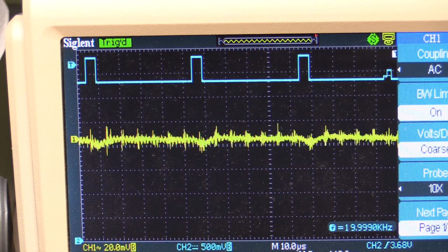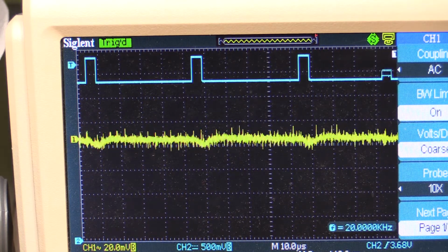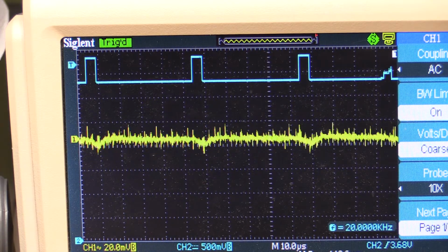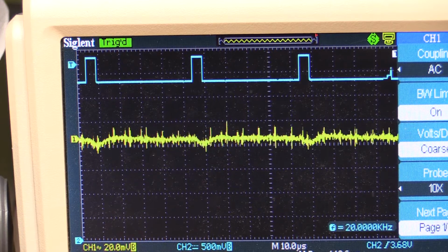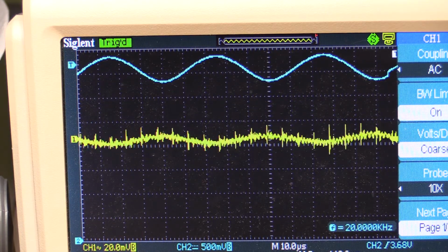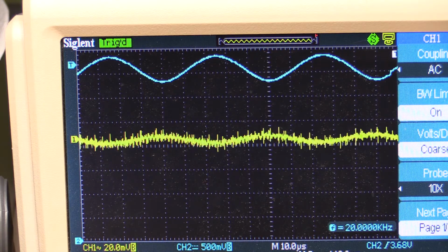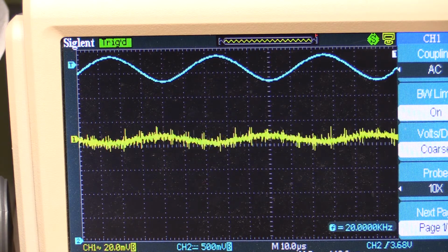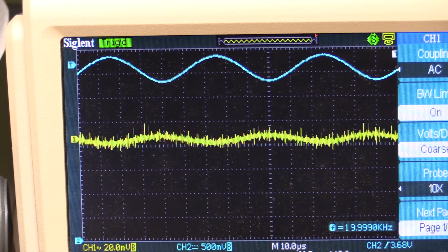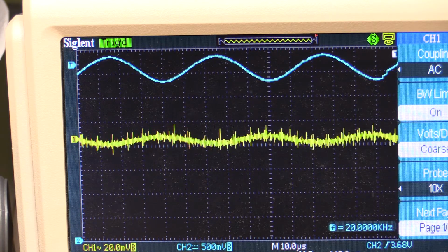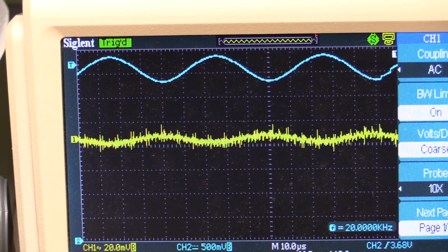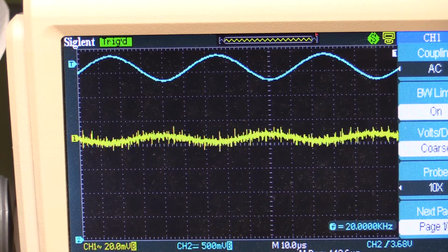It's not, from what I'm able to throw at it, from random noise, DC levels, if I put a sine wave at it, all right, you can see the output there is following it. Now, as I say, that's 20 kilohertz variance of 2 amps. It's following it by maybe 5 millivolts, which I think is pretty good, because the internal oscillator is running at apparently 700 kilohertz. I don't know if I can measure that anywhere.